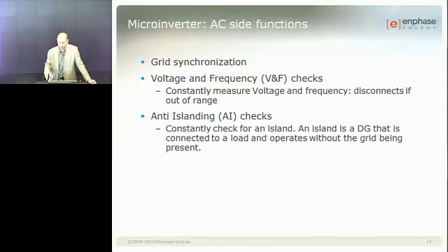We have to prove that we can island, and then we turn on the algorithm, and we need to disconnect within 2 seconds. These tests cannot be done in a passive way. I cannot just look at voltage and frequency and say, I'm islanded. It's not possible. You have to actually actively disturb the situation, kick the thing, and see how the system behaves. If you are connected to the grid, things are very stiff because the grid will impose a voltage no matter what. If you are on an island, you can kick it and things will move. That's a typical way to figure this out. It's quite a tricky algorithm to get right.